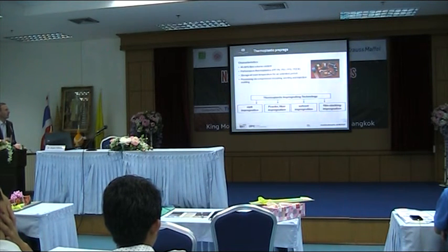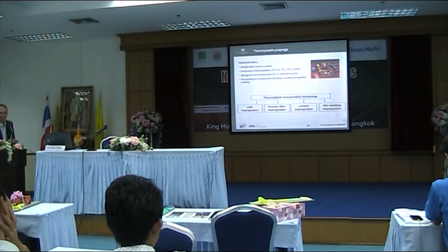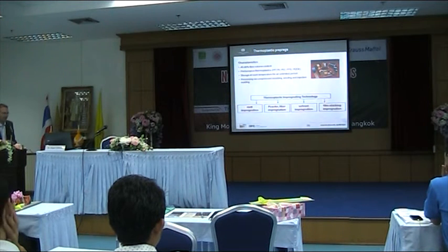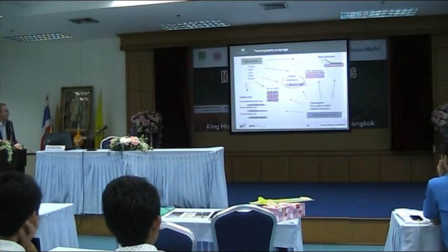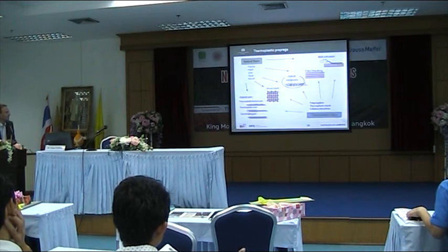Okay, so to make this impregnation, you normally have four process paths you can use, but especially common is direct melt impregnation, powder or fiber impregnation, so-called film stacking. We will go into this later on. And now looking at the premixes you can make with natural fibers, especially there is woven hybrid.